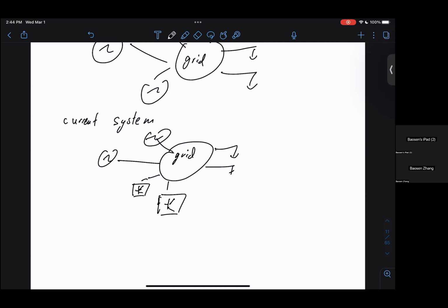Right. So the challenge with wind is, the grid is 60 hertz. How fast do wind blades typically spin, ballpark wise? Is it 60 hertz? Right, it's better not. Hopefully much slower than 60 hertz. So big wind turbine blades typically spin at something like 30 RPM, which is 120 times slower than 60 hertz.